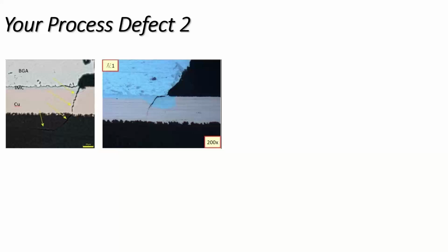Now, this type of phenomenon is quite often seen during vibration or drop testing. So if you're doing vibration testing or drop testing, particularly on thinner laminate materials, so if you're on a 1 millimeter laminate, yes, it's more likely than on a 1.6.